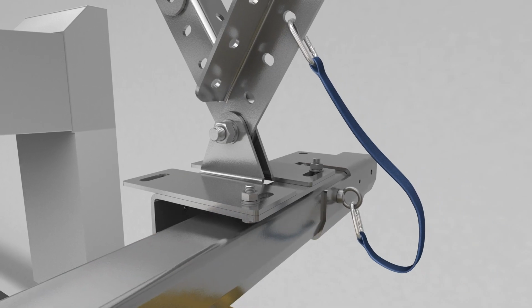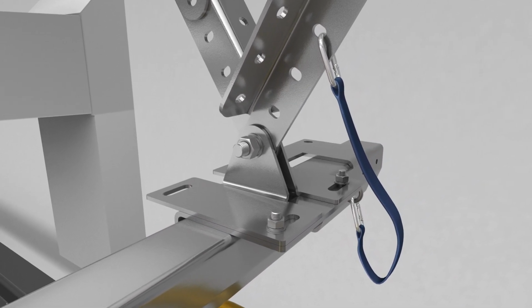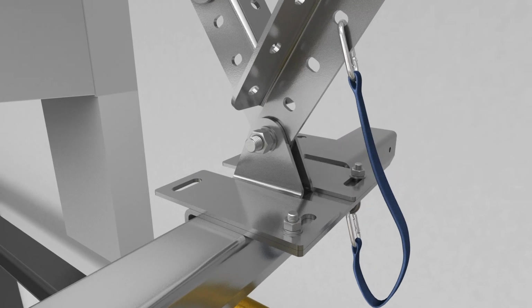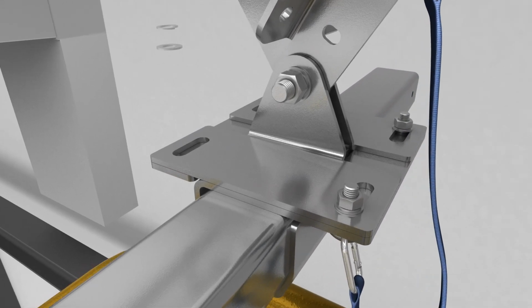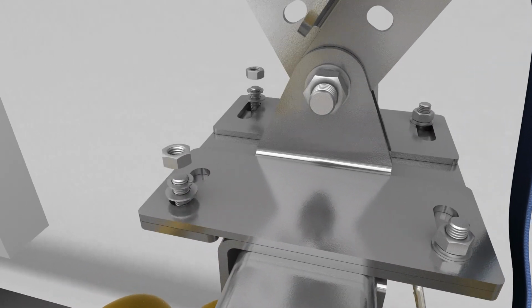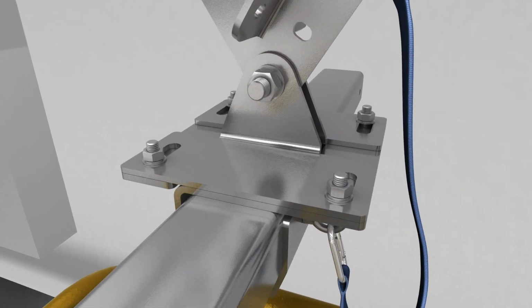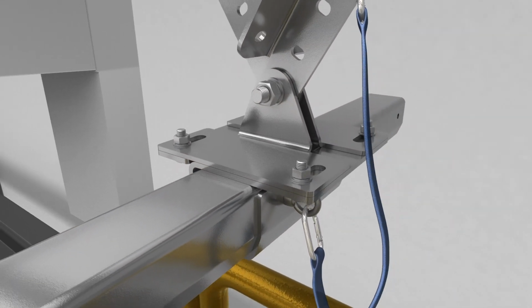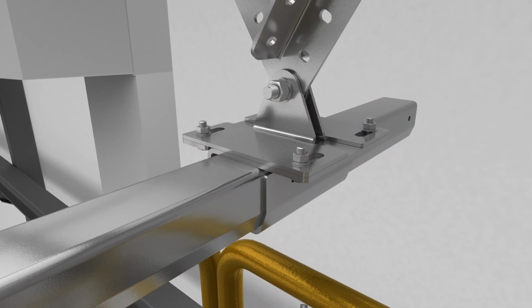As the rigid rail is inserted into the fixed half clamshell brackets, slide the additional brackets into the fixed assemblies. Secure the half clamshell bracket using two additional M12 40mm bolt assemblies and, where utilized, remove the temporary anchor point and tethers in preparation for installing any subsequent sections of rigid rail.